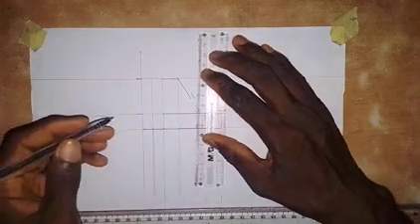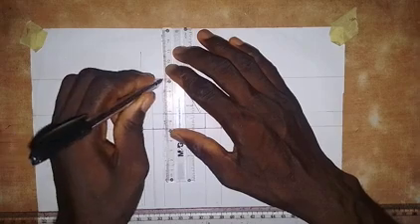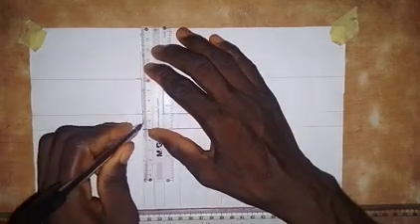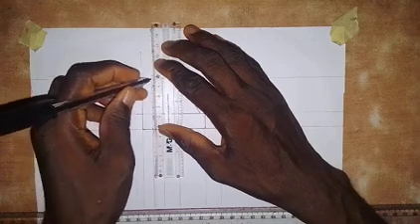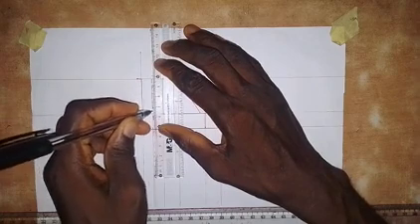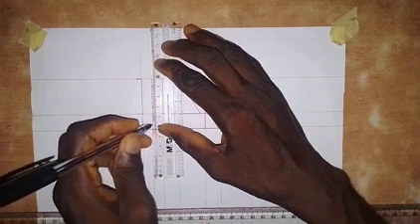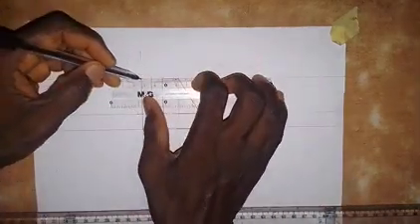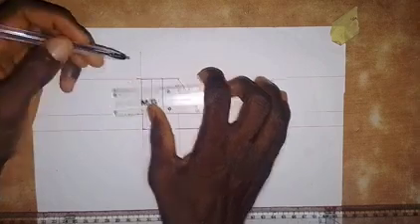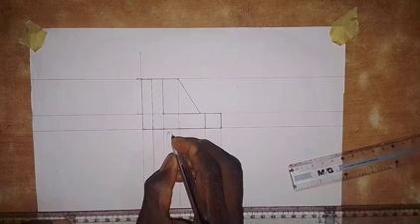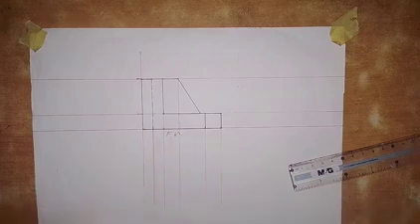When I'm done, I will talk about what we have done. So this line is a thick line, and this line also is a thick line, and this line we are going to draw with a short dashed line. This is the line that I said is hidden from us in the front view. And then make this line a thick line. Alright, so this is the shape of the front view here. So here we have the front view. Let me bring the object for us to see what we have done.